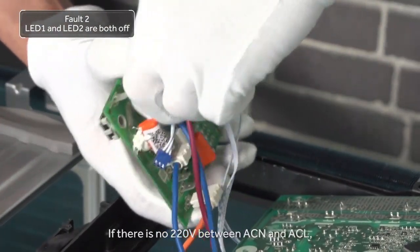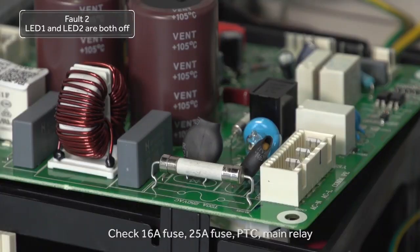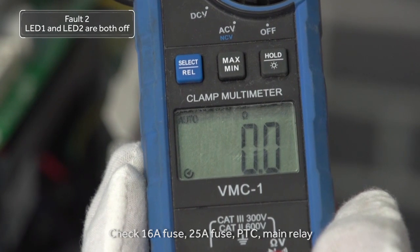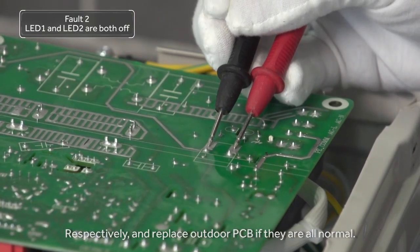If there is no 220 volt between ACN and ACL, check 16 ampere fuse, 25 ampere fuse, PTC, main relay respectively, and replace outdoor PCB if they are all normal.